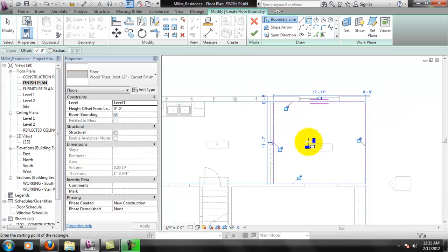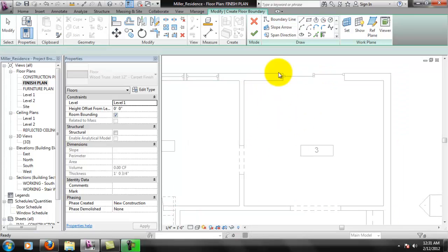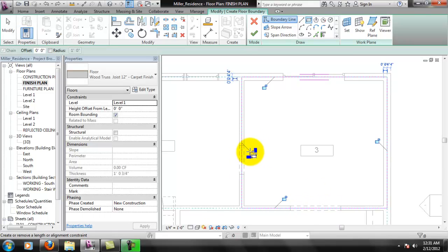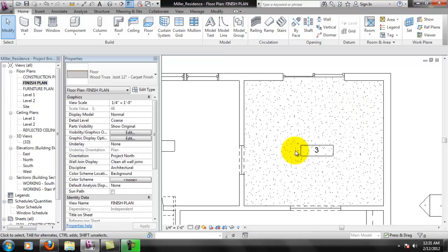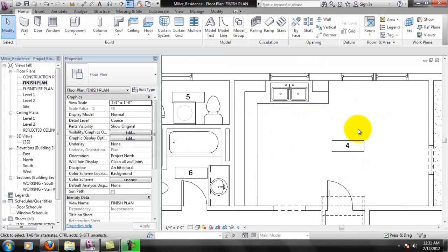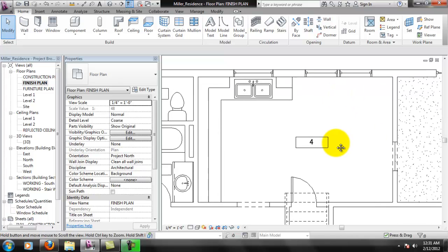yeah, when you draw your floors, the center line of your floor should be in the center line of the wall. So your rectangle should be like that. Your floors should meet in the center of your door openings. So those should be locked kind of there. Check that. And that'll drop a floor finish in there. Floor finish looks similar to the reflected ceiling plan.